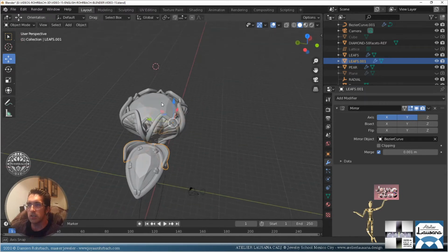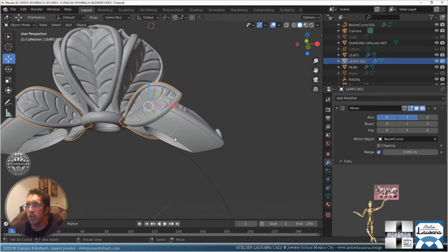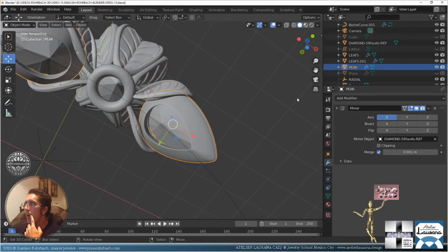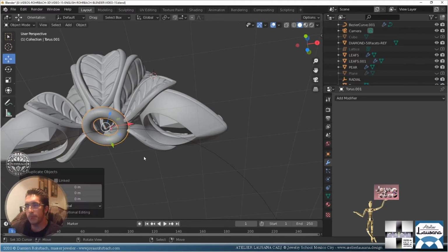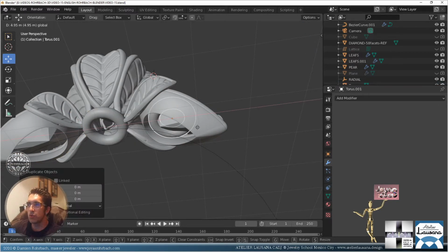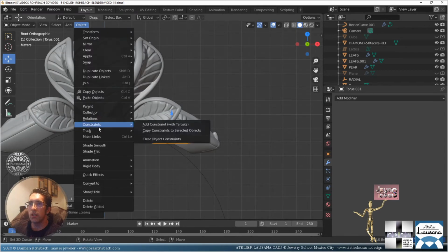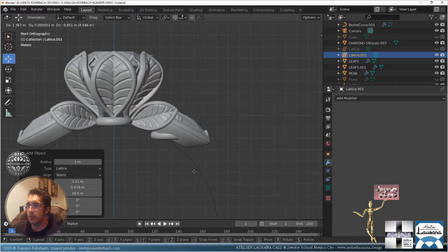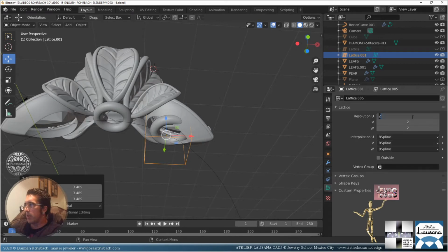Okay, nice. So now we need some kind of body for the ring. We also need here... Yeah, I do need a small border. So here I'm going to copy this guy and I'm going to use a lattice to solve that small problem, because I can't do it like that. All right, so let's bring in a lattice, add lattice here. Where's my lattice? Here. Let's make it bigger. Okay, let's bring it to 4, I guess.